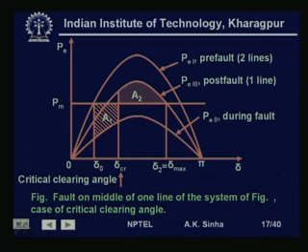The electrical output, in this case, is going to be equal to P max 3 sin delta, and we have the mechanical input, which is equal to P max 1 sin delta 0, that is this point.